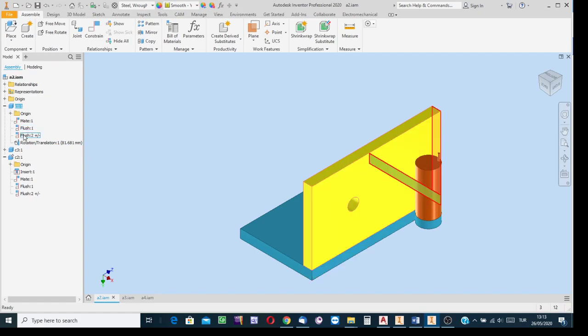And then see which constraint has been input for positioning the yellowish one with respect to the cyan colored one, the blue one, to find its place between those limiting positions. Bring the cursor onto this icon or onto the icon of the other component. These are to find the same things. They bring the same dialog box. Whenever a constraint is input for one component with respect to the other, the same constraint icon is attached to the associated lists.